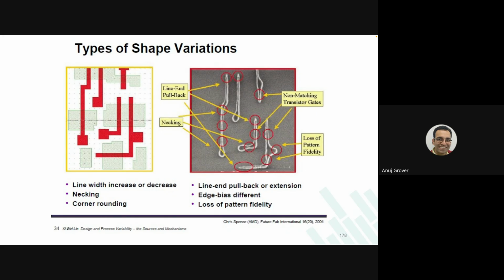Rows and columns both. Word line end cells, bit line end cells, all of them. We have to put them so that we are able to ensure that whatever rule violations we have done inside the memory array, they do not impact memory functionality. Otherwise, those edge memory cells will behave very differently from those in the center. So you do not let the edge cells be used at all.